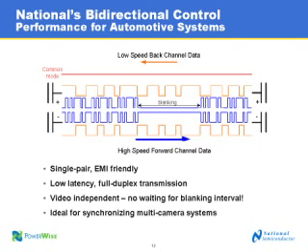So as we mentioned, there's no waiting for blanking intervals, and this really makes this ideal for situations where you want to synchronize, for instance, multiple cameras. So you want to send out a synchronization pulse from the host controller to, say, 3 cameras on the far end. This can all happen without being dependent at all on video timing.